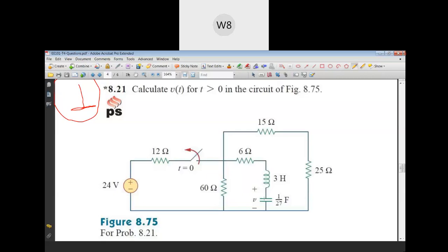and then the flow of the current will start putting charge on the plate in the reverse direction. That means the bottom plate will start becoming positive, the upper plate will become negative. So the energy in the form of magnetic field will start getting converted into the energy in the form of electric field inside the capacitor, and ultimately there will be a fully charged capacitor and zero current or zero magnetic field in the inductor. So this phenomenon keeps on going, electric field to magnetic field, magnetic to electric field conversion.